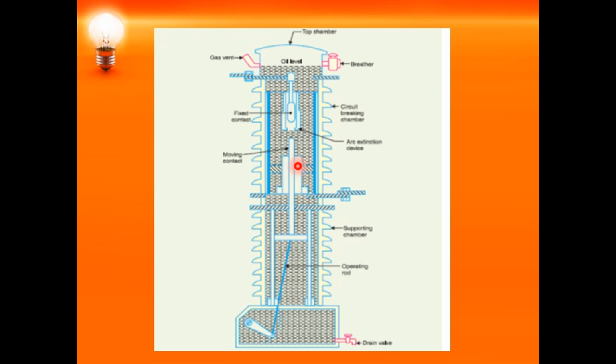So you have seen the various types of oil circuit breakers which are available. The plain explosion pot kind is used to interrupt low magnitudes of current. The self-generated pressure oil circuit breaker is used for both low current as well as high current interruption. Then you have a double break type oil circuit breaker, which can be used to interrupt low magnitudes of current, lower than the rated maximum value. Next, you have the bulk oil and minimum oil circuit breaker.